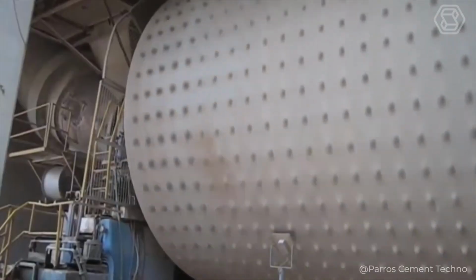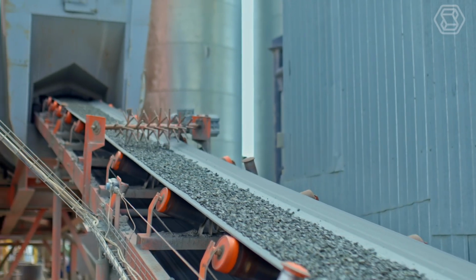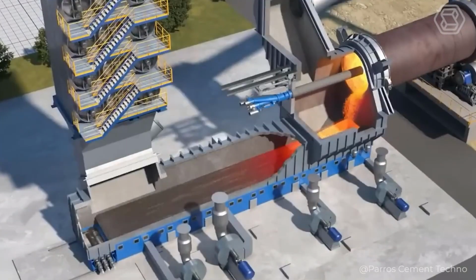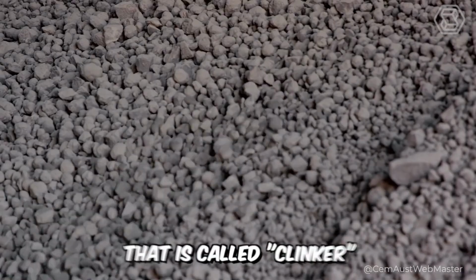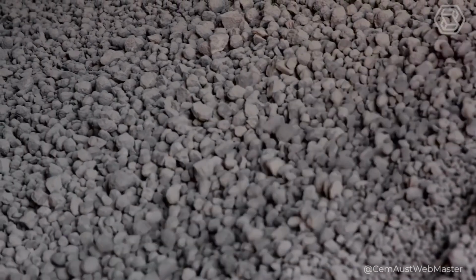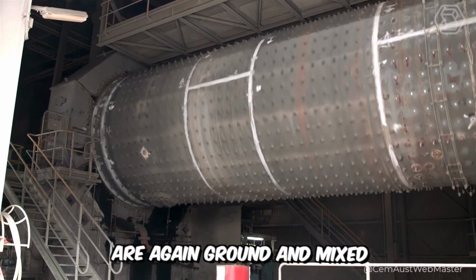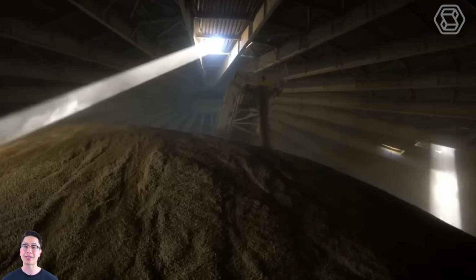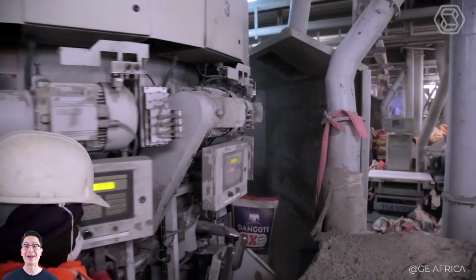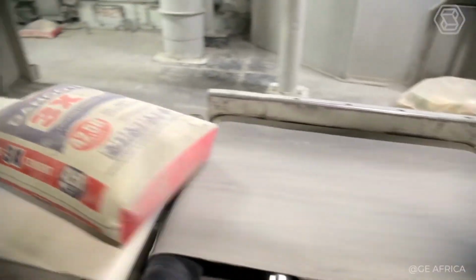The components are combined and mixed, or more scientifically, homogenized. The output can then be homogenization silage, or raw meal, which is sent to the kiln to undergo a delicate roasting process. It is this fired material that is called clinker. The next stage is when various necessary additives are added to the clinker, depending on the type of cement, after which all components are again ground and mixed. Finally, the obtained raw materials are sent to the prepared hopper for storage with the help of special machines. There, the cement is packed into bags of different capacities, and then it's sent for further shipment.